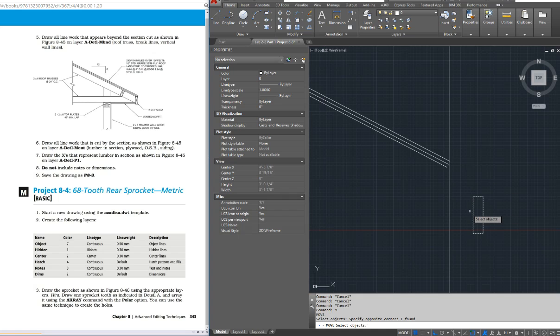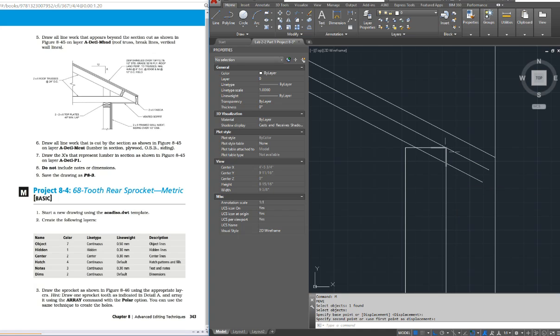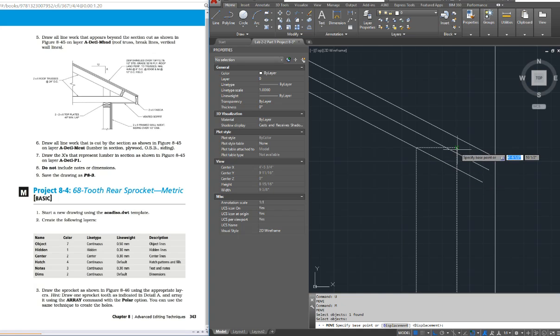So I'm just going to move that from, I'll just move it somewhere nearest. That's going to let me, nope, that's not good enough, because if you look right here, the shingles should hang over. So I'm just going to move from that intersection to nearest up here a little bit. Nope, my mistake. Down a little bit. There. Okay, that'll work good. So now those shingles are going to hang over a little bit. I think I'm just going to move that in so that that intersection's touching there. So to do that, I'm going to move from here to here.